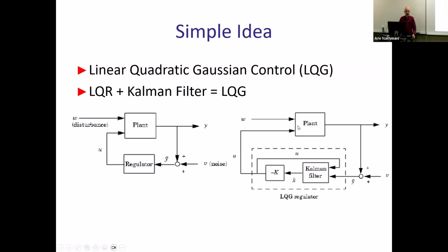This is input to the plant, which is control effort of the plant, right? And this might be some sort of transfer function. But I can take that input and return it back to Kalman filter, because what any observer or Kalman filter needs, it needs input and output, right? To correct for it, to compute the state. So observer, you can think about that as two inputs, one output system. In general, any observer, not only Kalman filter. So you're getting input and output as inputs to your Kalman filter or any observer, and the output will be estimated state, right? This is how it works in general.